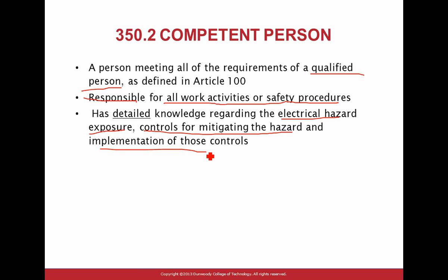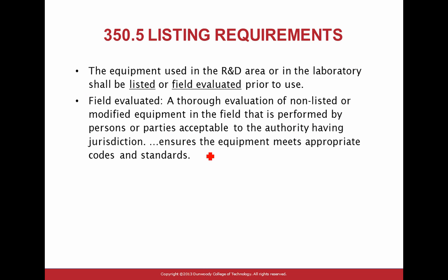So now you're getting into a lab and research. There's a lot of things. This is not just a panel. There's a lot of energy that can get in. So you have to have detailed knowledge of what's going on in that lab. Listing requirement: all the equipment that has to be used in the lab must be listed and field verified. Listed and field verified. That was on the test.